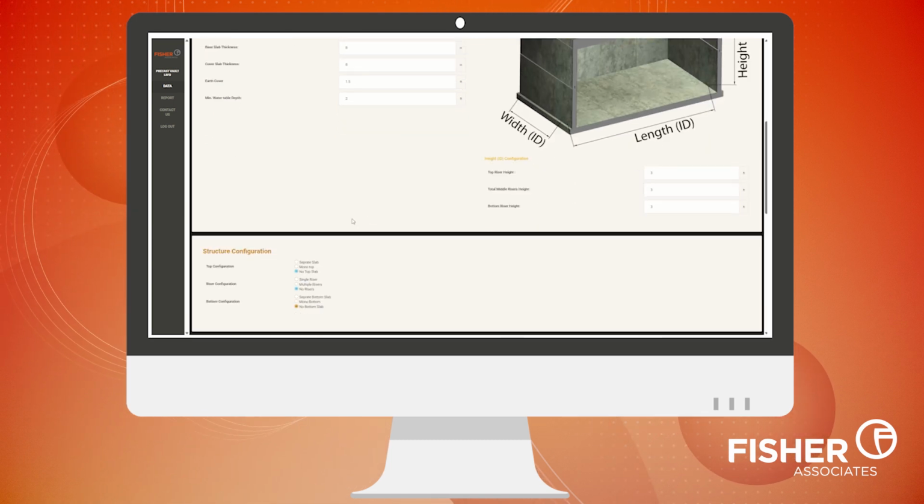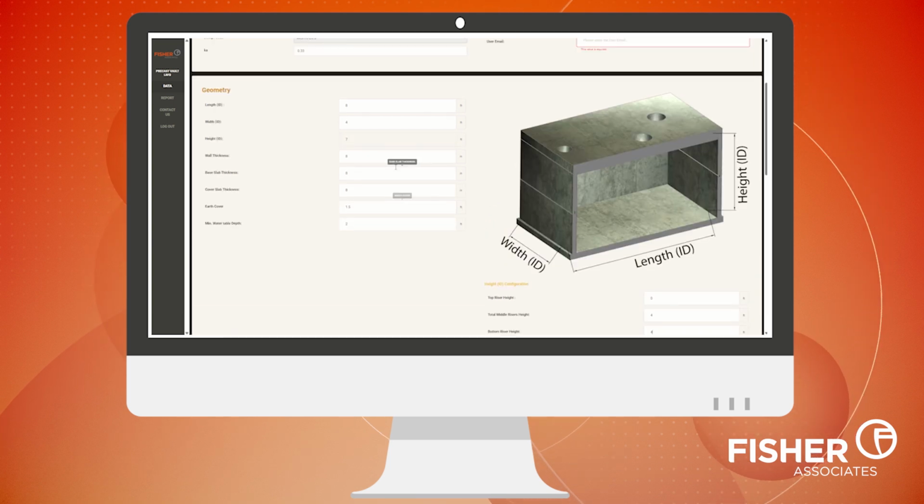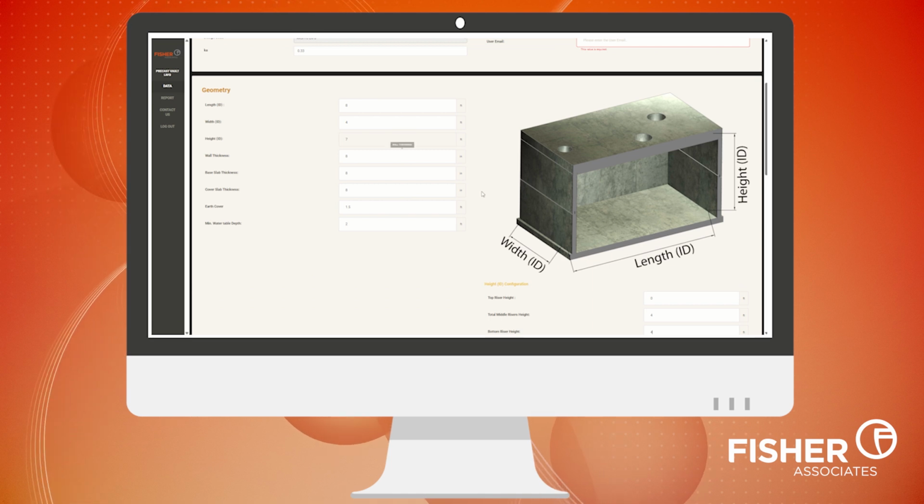At the bottom right, you'll find fields for height configuration. Enter the measurements as 0 feet, 4 feet, and 4 feet. Keep in mind, with a wall thickness of 8 inches in this example, the sum of the last 2 fields, 4 feet plus 4 feet, equals the wall thickness.